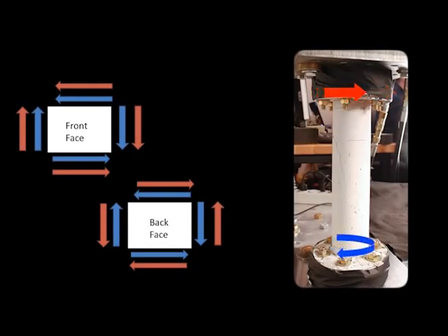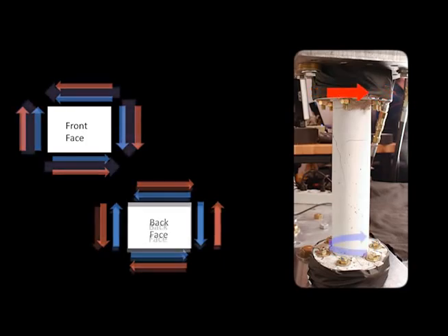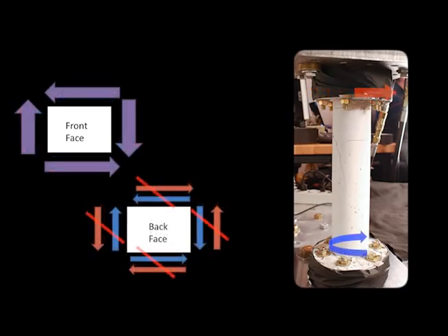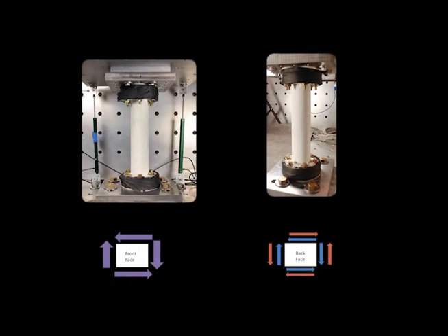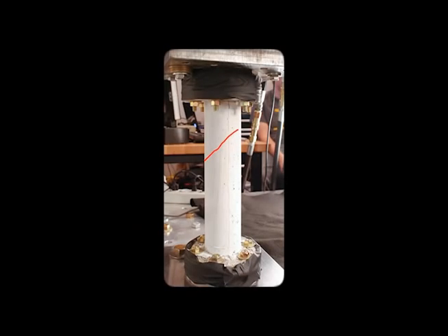When a member is subjected to a combination of shear and torsional loads, the stresses due to shear and torsion will be additive on one face, while counteracting each other on the opposite face. It is expected that the first crack will appear on the side of the specimen where stresses are additive. Cracks will initially travel diagonally along that face. The nature of their propagation will depend primarily on 2 factors: the type of behavior, shear or torsion, which controls the individual test case, and the reinforcement provided.